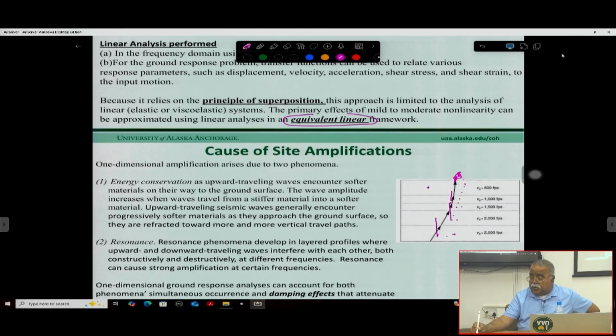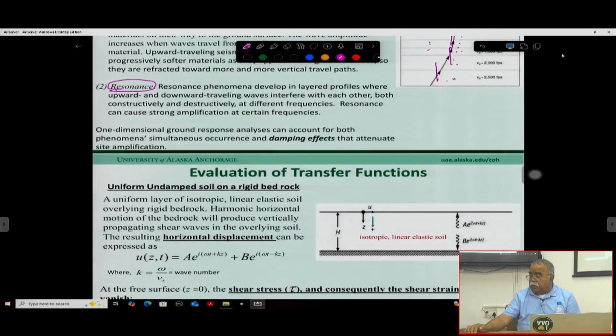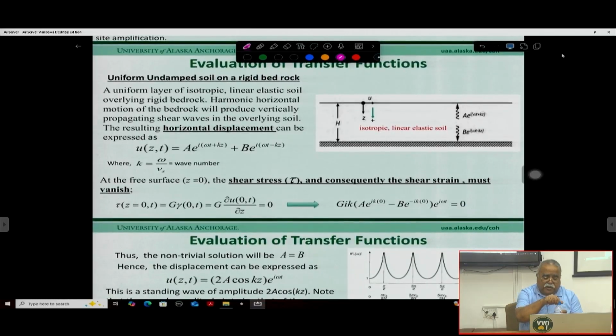So now what has happened is that due to the stress wave, each layer has its own frequency of vibration, and it might be possible that due to this propagation there will be some resonance effect. That effect will create a lot of vibration in the soil, and we need to test whether it will produce a significant vibration of the soil during the wave propagation or not. Okay, so very first, simple.